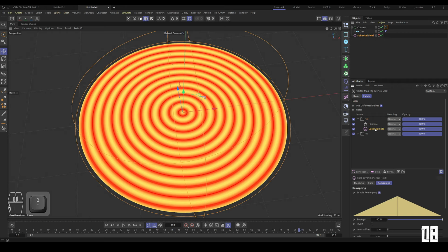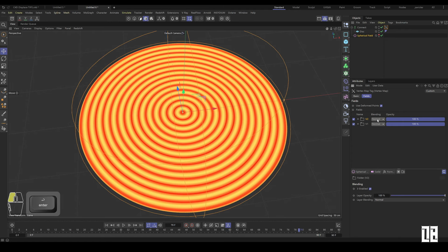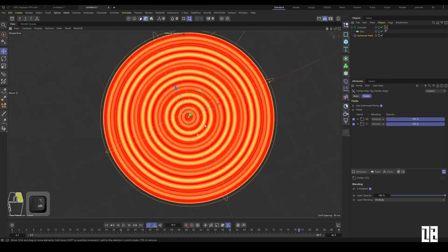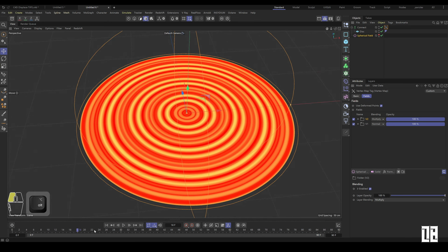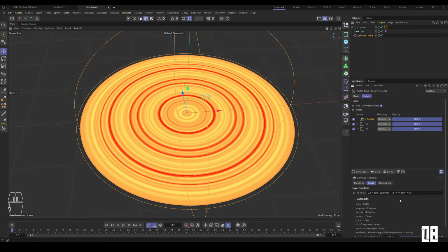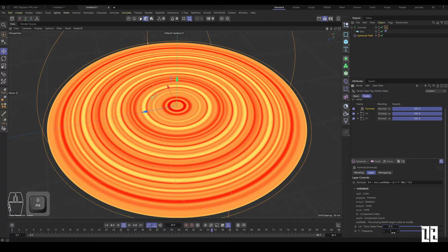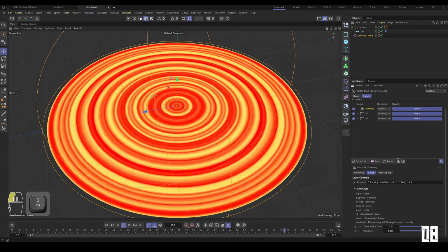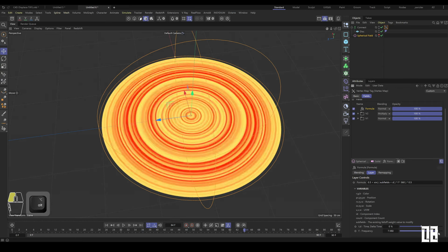Expand the folder and modify the Formula Filter parameters. Select the folder in the upper layer and change the blend mode to multiply. Now for the Vertex map, a randomly sized ring appears. Continue to add formula filters on this basis and see what happens. First change the time to 0 and then adjust the frequency. Now the random effect is even more obvious.